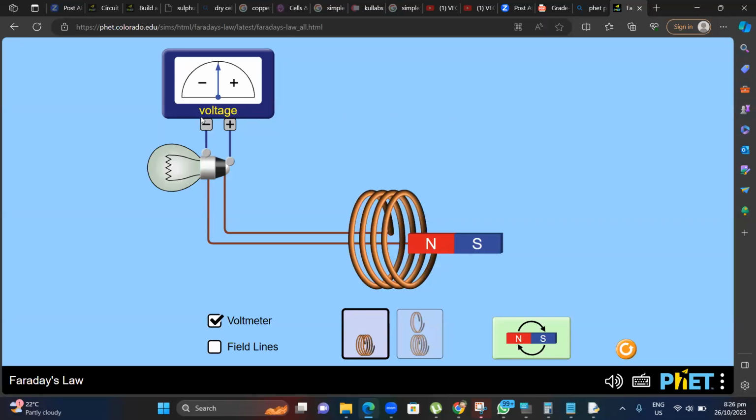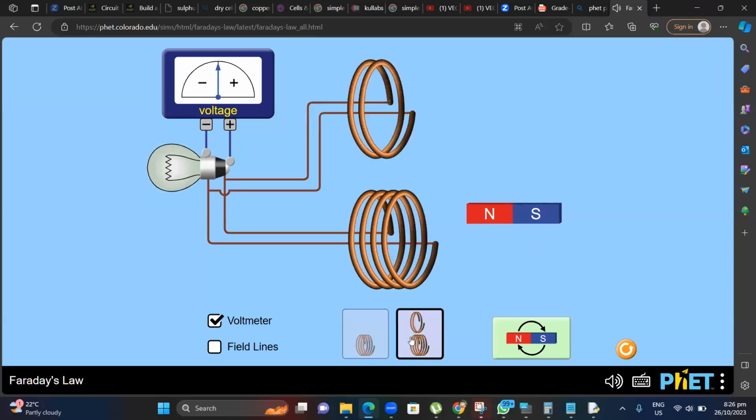The LED basically supports only DC current. So if it is connected to AC, the LED will turn on when plus and minus are correct, and when they are wrong, it will turn off. Therefore, if this dynamo continues to rotate, the LED will blink only in one direction, but you can see the filament bulb blinks in both directions.